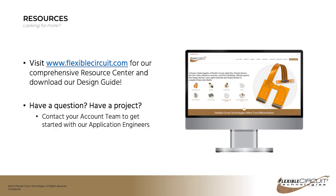A very common method of terminating flex circuits is a ZIF connector, a zero insertion force connector, and they're very inexpensive. Instead of having two mating connectors, you will have the ZIF connector on your rigid PCB and then basically just a pad pattern on your flex that goes into that connector and then it's clamped down. And they're very reliable. I've seen them used in applications ranging from helicopters to cell phones. They're inexpensive, and like I said, you're getting rid of one termination method there.